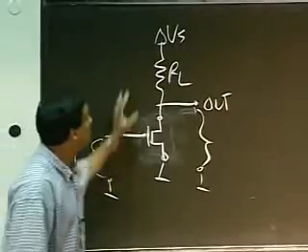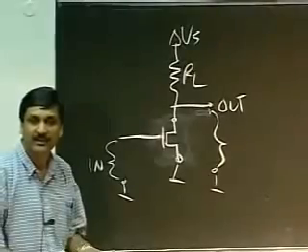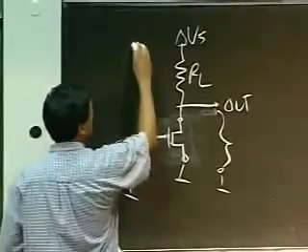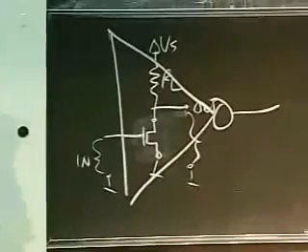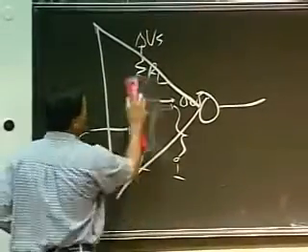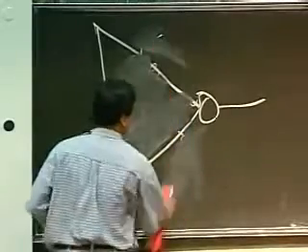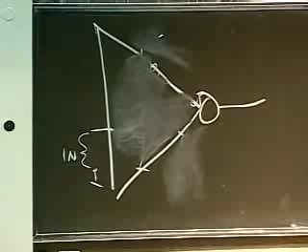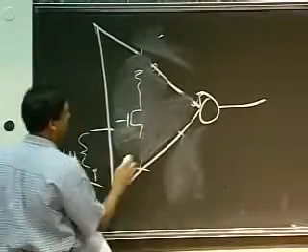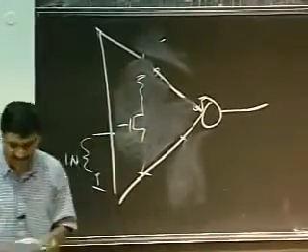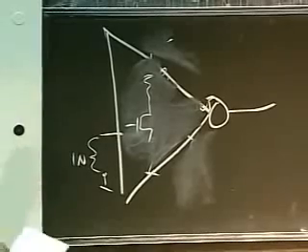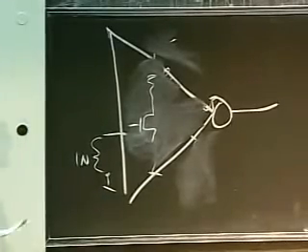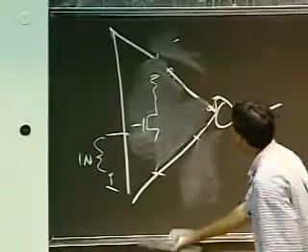Okay, so at 6.002, you can look at this and say, aha, that is an inverter. When you go to 6.004, what you will do is build this triangle and a circle around it, and you will ignore what's inside, and just look at that. So in 6.002, we showed you that the internals look like a pattern with a MOSFET and a resistor, but it's really the abstract inverter looking in from the outside. So this kind of closes the loop on inside a digital gate, and this was inside your little inverter with a resistor and a switch. Let me continue with this for a little longer here.